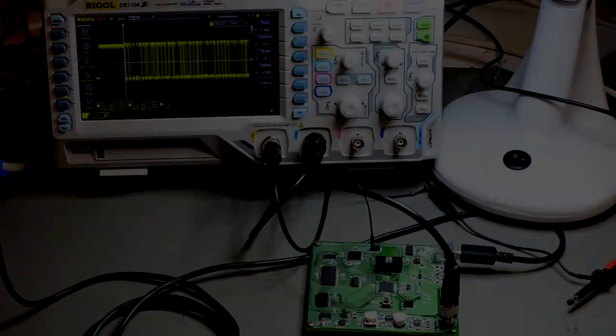So when you have the knowledge of the DSO, then you have confidence. If you know at the block level what is happening, even if some signal is not coming, you know which block has the issue. So when you are testing, you should have that block level diagram in front of you. If you are not getting a signal, you can say, okay, in this block I got the issue, then go back to the block level diagram and fix it. If your DSO is working straight away, maybe you are unlucky because you are not going to learn much. But if your DSO has some issues, then you will learn a lot.